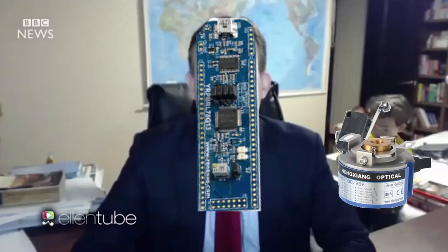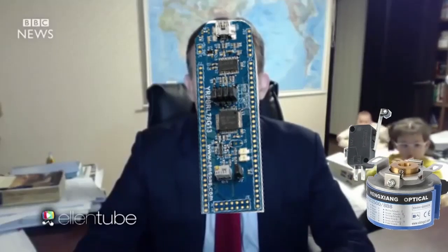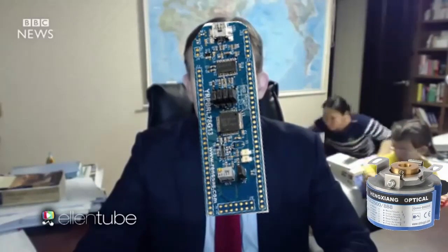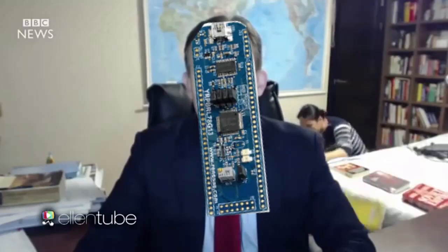So the program's running through its normal sequence of code, then there's an interrupt, it stops by that line, it handles the interrupt, and it goes back to that code again. So you need to ensure that if that encoder is spinning at its max rate, in other words the turret is flying across, and your processor is being hit with interrupts the whole time, will you saturate the processor with the interrupts so it can't even calculate the next control signal?